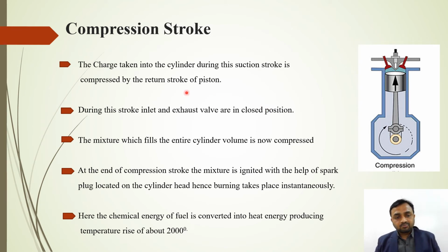Compression stroke. In case of your compression stroke, the charge taken into the cylinder during the suction stroke is compressed by the return stroke of the piston. The charge which is taken inside the cylinder in the suction stroke is compressed in the compression stroke. Second point is during this stroke the inlet and exhaust valves are in closed position. In case of your compression stroke, what happened? Now your inlet and exhaust valves are in closed position.